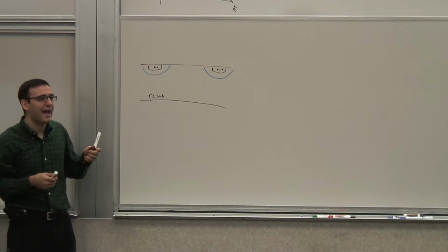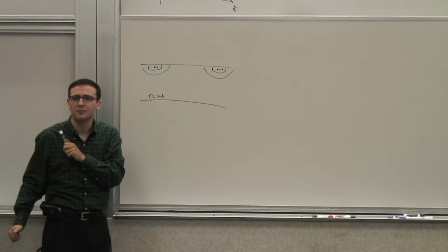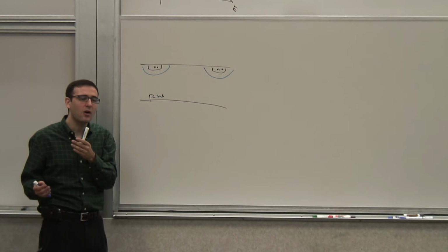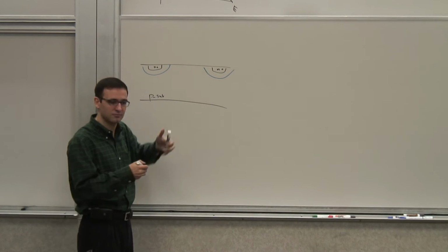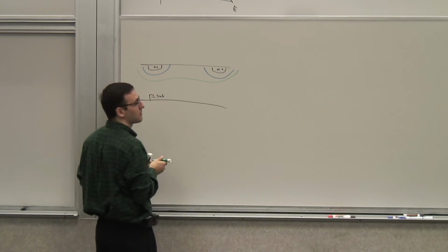So I have a little bit less depletion region to make when I apply my VGS. That effect always exists. But for a long channel transistor, this is a small fraction of the total depletion region that I have to generate. I have to make this much depletion.